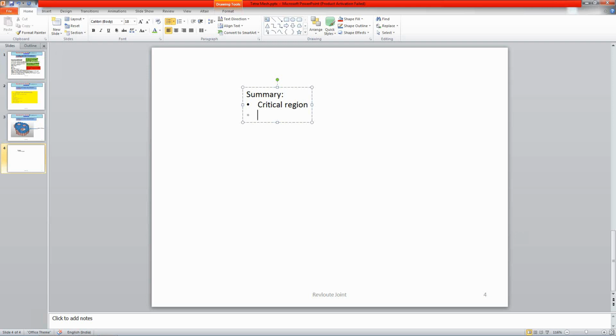Planar area you can maintain with equilateral trias, and check with free edges and T connection, right? So you can check these things using Shift F3.